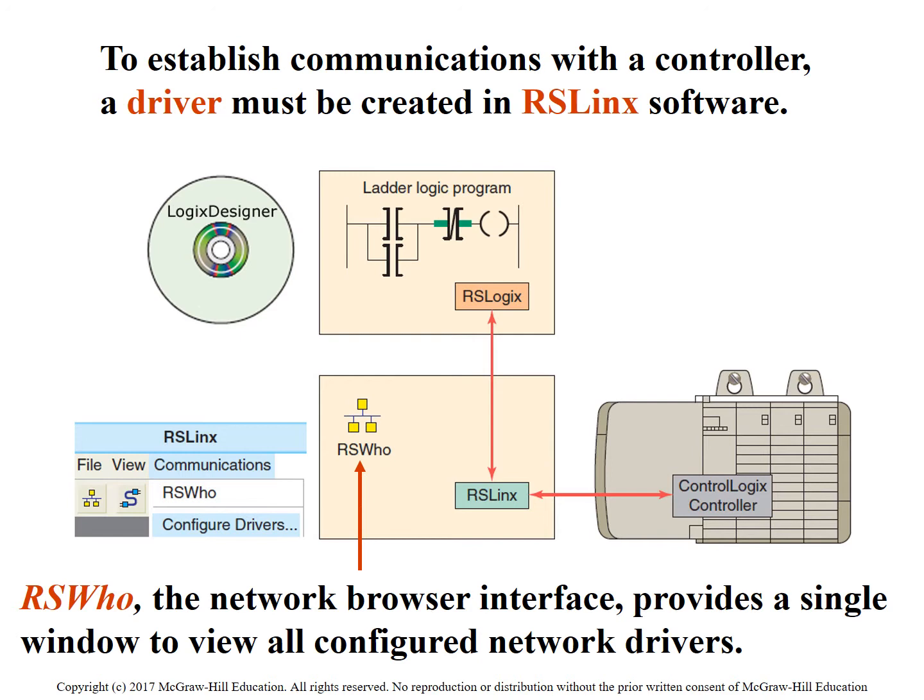One of the points they're also noting here is that they still use RSLinx. I didn't get into too much detail on this, but RSLinx is a software that Allen Bradley has developed to set up communications with PLCs to laptops and computers and whatnot. This RSLinx still runs in the background with the 5000 series software.